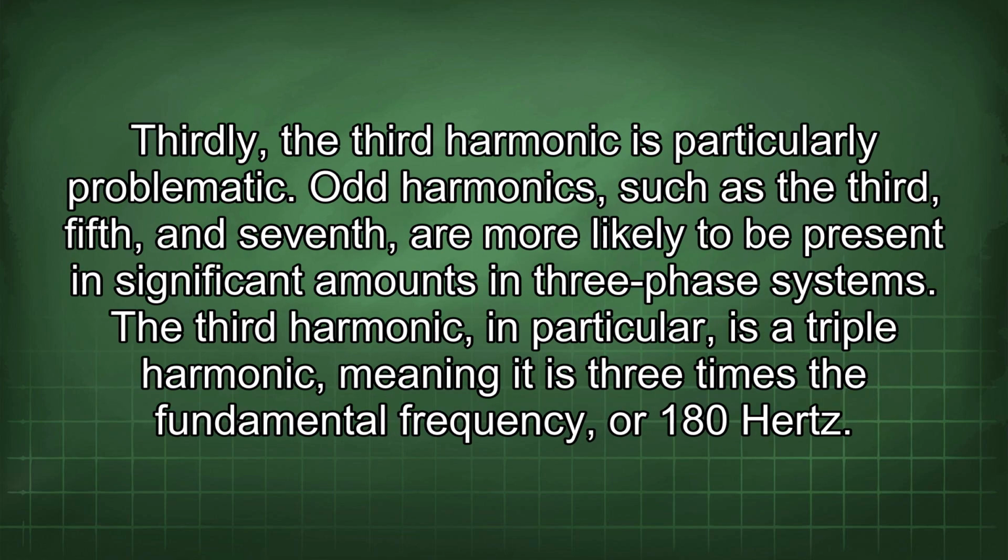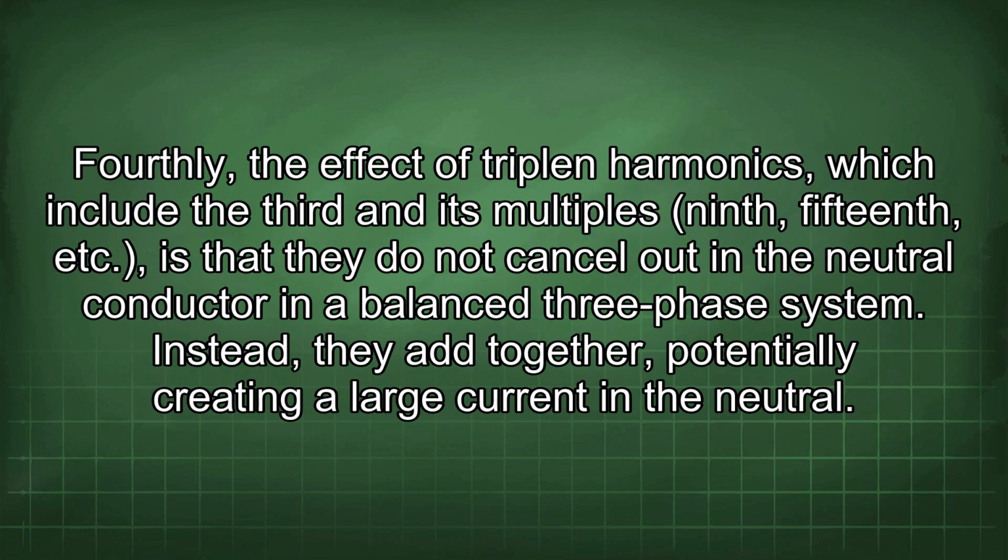Thirdly, the third harmonic is particularly problematic. Odd harmonics, such as the third, fifth, and seventh, are more likely to be present in significant amounts in three-phase systems. The third harmonic, in particular, is a triple harmonic, meaning it is 3 times the fundamental frequency, or 180 Hz. Fourthly, the effect of triplen harmonics, which include the third and its multiples, 9th, 15th, etc., is that they